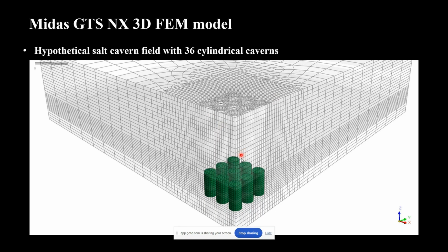And the way these caverns are built is by solution mining techniques. So basically, we drill a well and we start injecting water. This water dissolves the salt and we pump up the brine. Brine is basically the water fully saturated with salt. And then we can easily build incredibly large volumes underground.